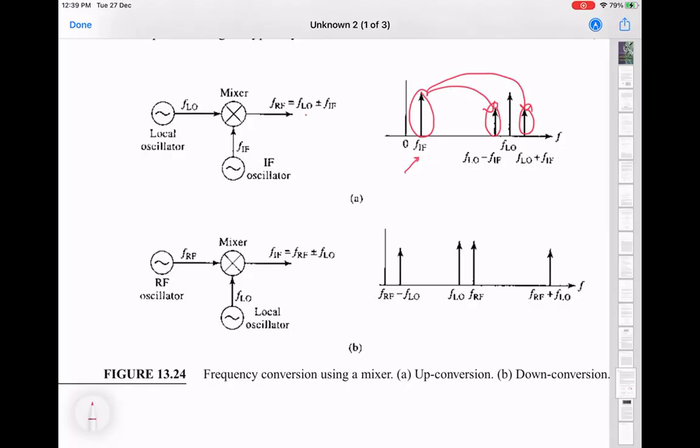Now, you have seen this probably even in high school in the context of AM modulation, right? This actually is nothing but AM modulation, because what does multiplication mean? You have one term multiplying the other, which you can equally say is that one of the frequencies is acting like the amplitude of the other frequency term, right? Even though when you talk about AM modulation, there's something called the modulation index.